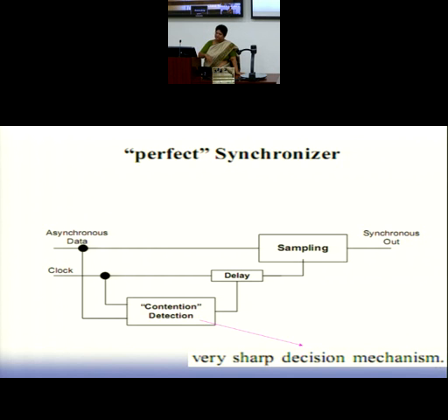That's what I am saying. You need to design again. It will lead to skew. Every design that you make has its own repercussions, naturally. You have to now design a separate edge for yourself, which aligns itself with the master edge, which cannot be totally away or misaligned with the master edge. That is not possible. Otherwise, ultimately, when the data is latched, how will you align yourself to the system clock sequence?